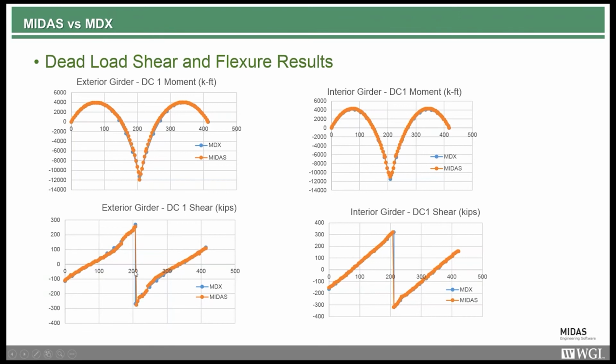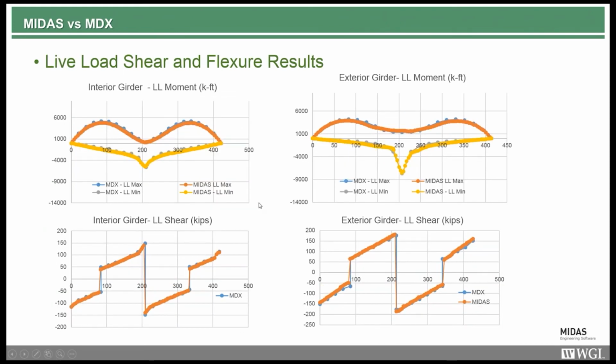So this right here is the exact reason why it's important to have a good understanding of deck pouring sequence. Because if we were to look at our results for just a single deck pour, what you would see is a perfectly symmetric W shape here. And so therefore, we could be analyzing the wrong camber information, and we might have to make costly profile adjustments in the future. So always be careful about considering deck pour results during this.